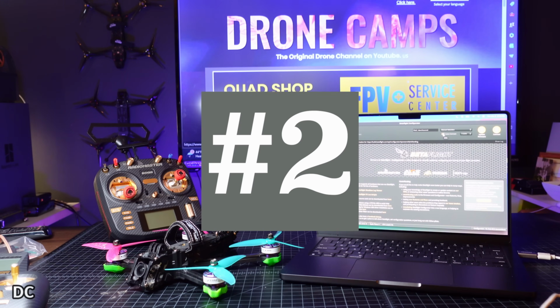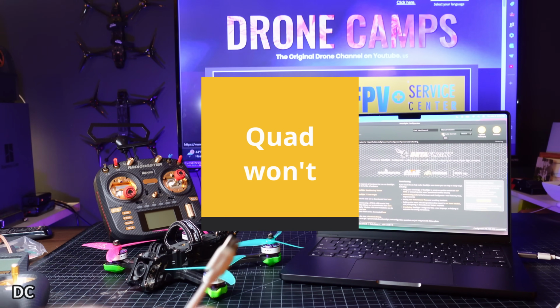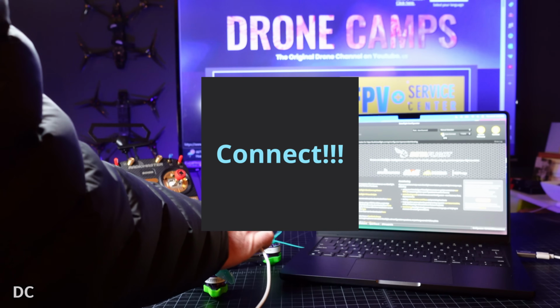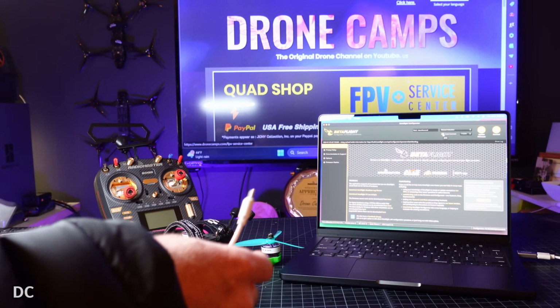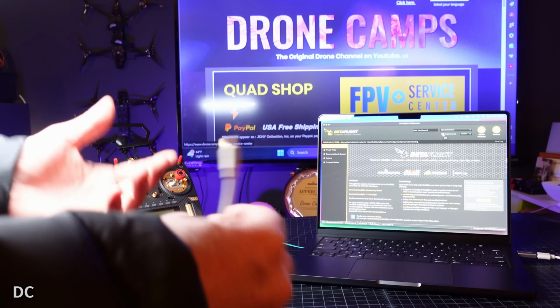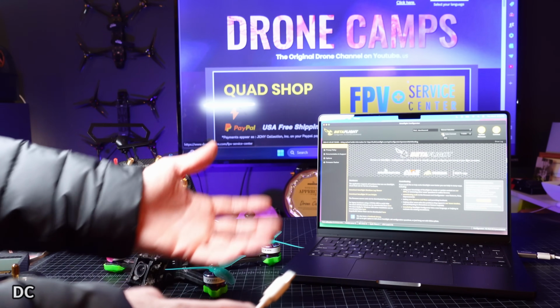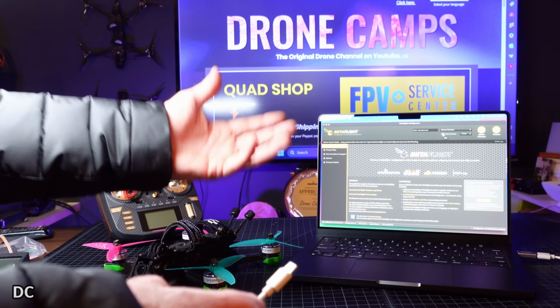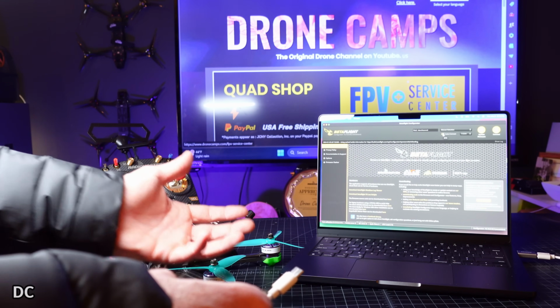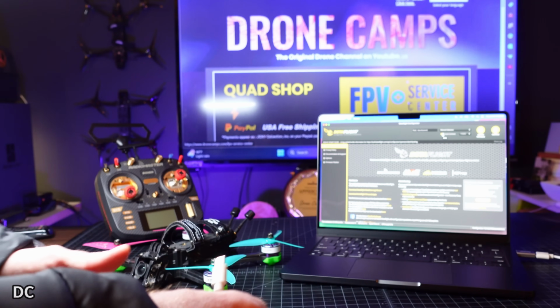Now, a very common problem that a lot of people have after they get Betaflight installed on their computer is they just can't connect to their flight controller and get the quad to load up inside Betaflight. This is such an easy fix. If you're on a PC, you've installed your drivers, Betaflight Configurator is installed, and you restarted your computer. If you're on a Mac, you don't have to worry about drivers. You just need to copy the application over to the applications folder.